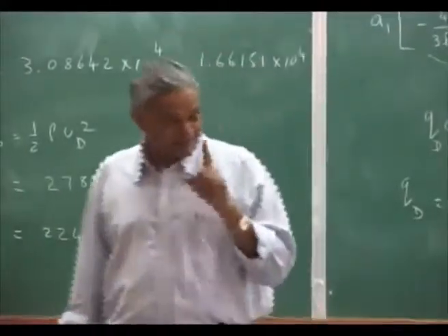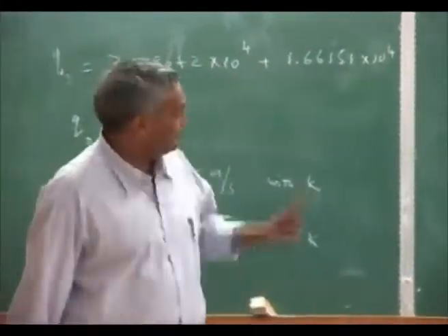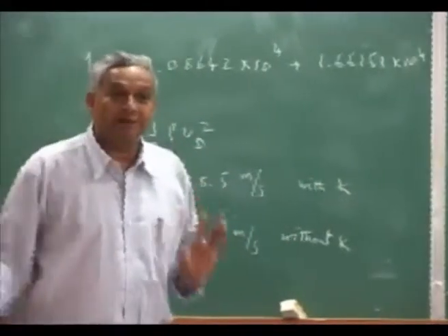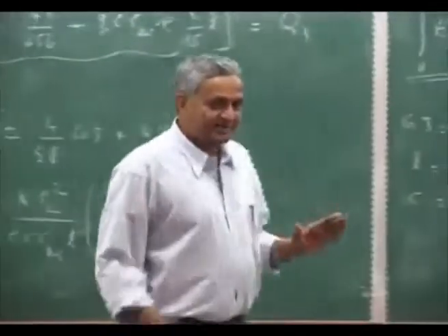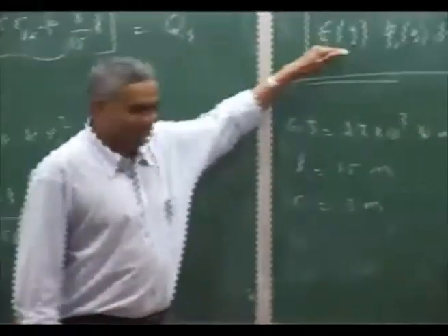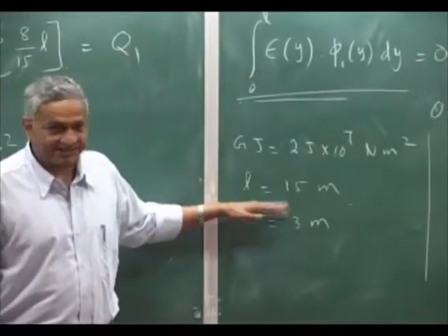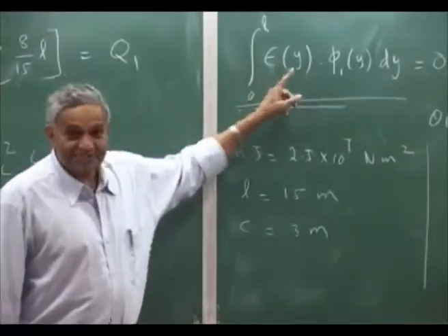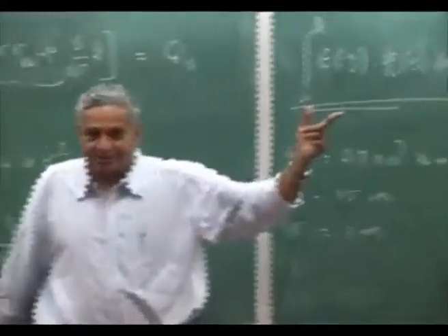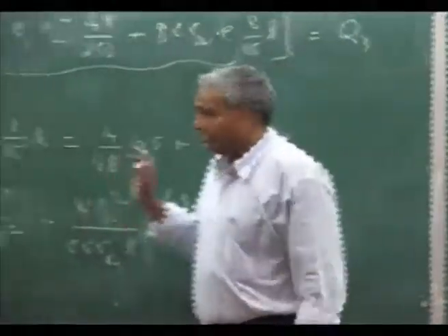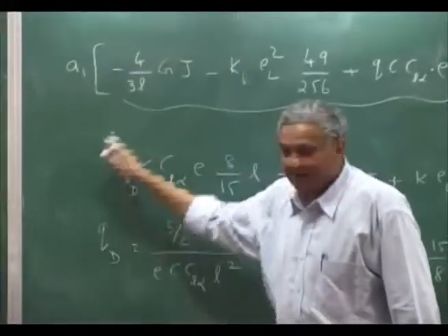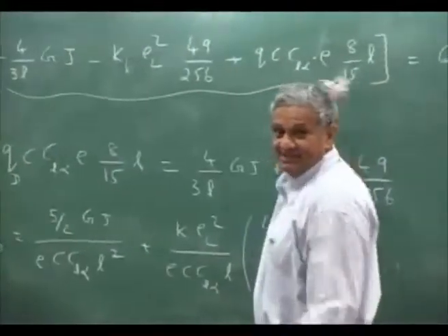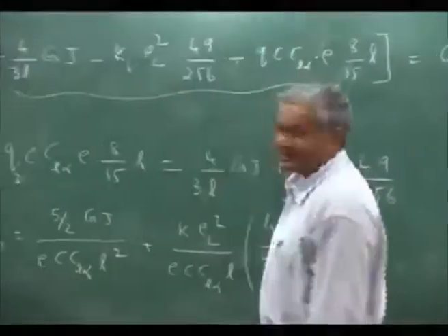That is why solving that problem is a little different from the straight wing problem. Please understand; that is why when you apply Galerkin, understand thoroughly. You will have a bending equation error and a torsion equation error. Multiply the bending equation error by the bending assumed function. But you will find the constants. What is it finally landing up with? A1, A2, like that. Because this is only one equation, this is set equal to 0.